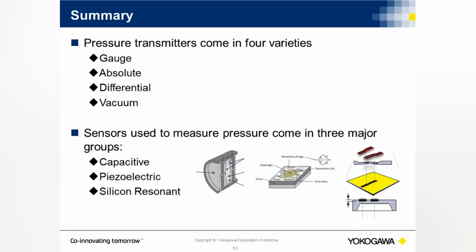These are composed of two H bridges, which resonate at 90 kilohertz. As the pressure is applied, one goes into compression and the other one goes into tension. And eventually, the frequency difference is amplified by the applied pressure.